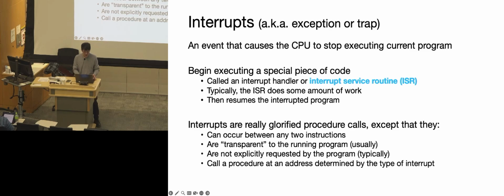So, interrupts. We're going to call this an interrupt service routine, an ISR. This is typically like a handler or a function call that occurs when the interrupting event is happening. And then the main program will break out and jump to that, do something, and then come back.